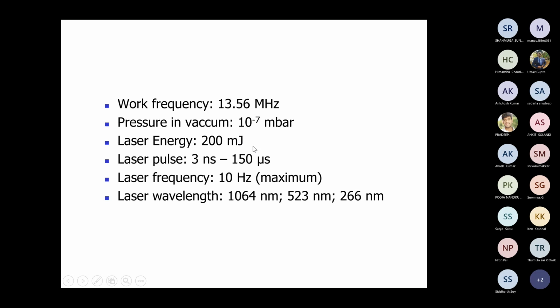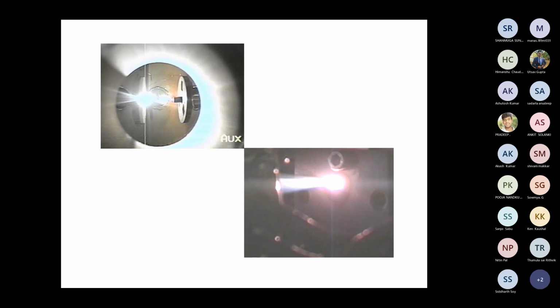Laser energy is 200 millijoule, laser pulse 3 nanosecond to 150 microsecond, laser frequency 10 hertz maximum, and different laser wavelengths can be used.